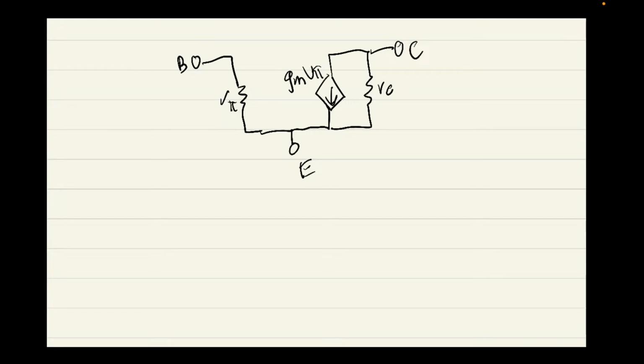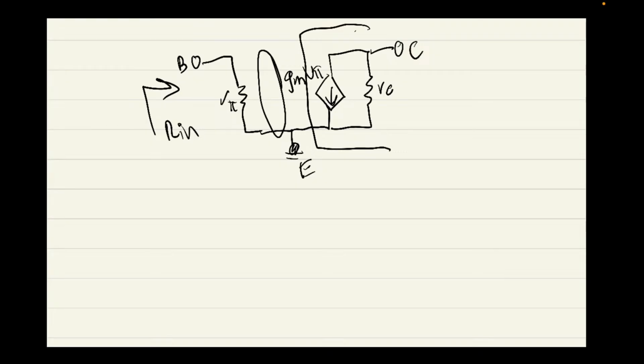What you can see is that there's an empty space here. A lot of the time this will be grounded. And so what that allows you to do, when you do your circuit analysis, if you have some sort of transistor or amplifier, and you're looking at Rin from here, is that the second part doesn't really influence it. This part right here doesn't really influence it. And if you look from R out, the first part here doesn't really influence it. Now, this is pretty hand-wavy. I'll get into something more rigorous when I do an example, but that's the general gist.